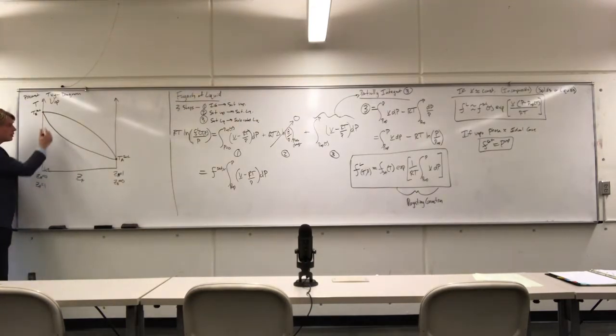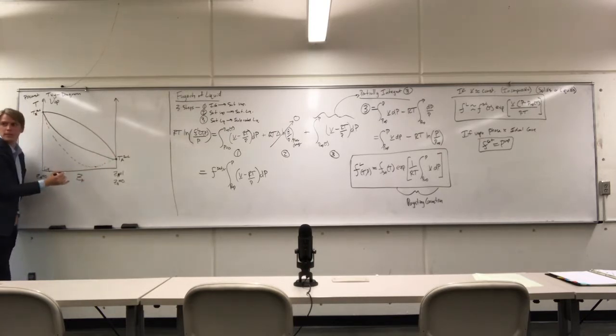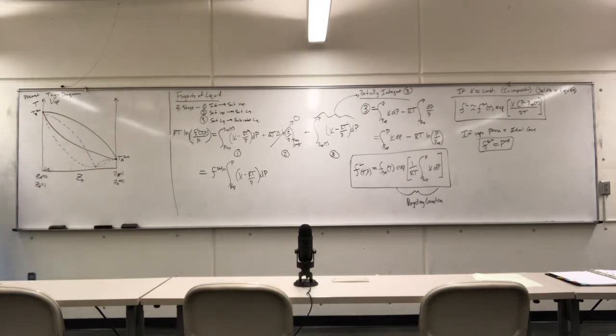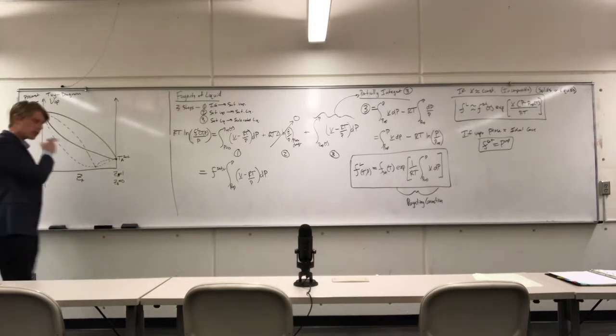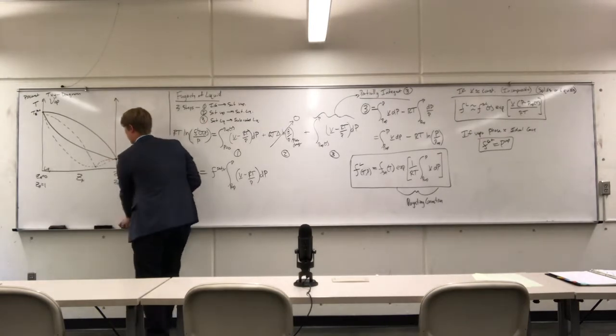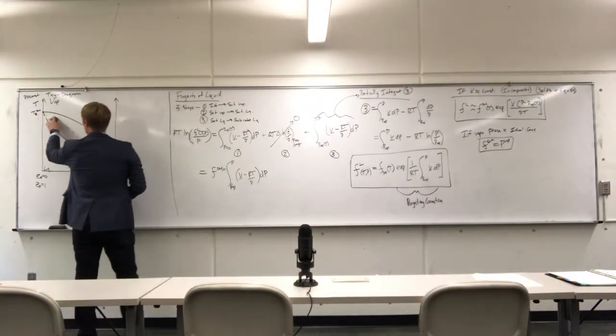An azeotrope looks something like this, where you've got a minimum or a maximum. You can get all sorts of funky shapes in TXY diagrams, because real fluids behave very, very complexly. Okay, so let's ignore the dashed lines for the weird non-ideal fluids that are not going to be the topic of discussion.